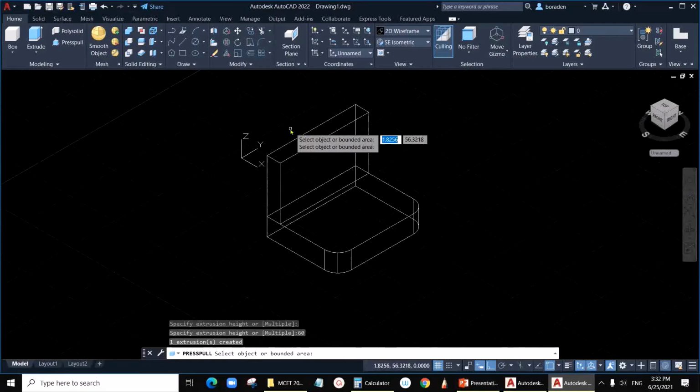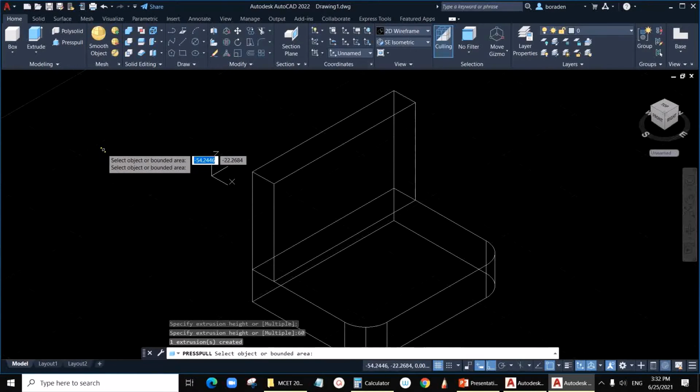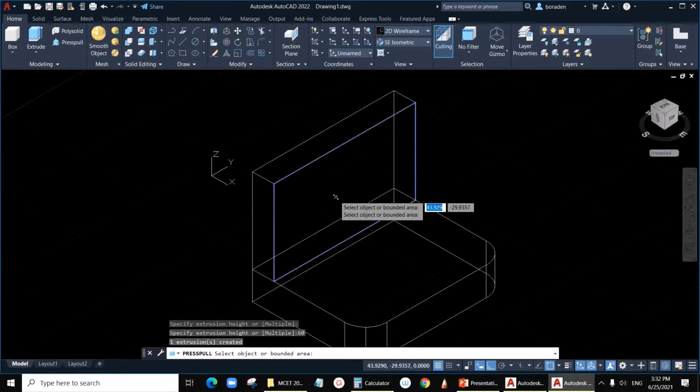Okay, so at these 2 points I will draw the circle of radius 20, but now this is my YZ plane. I want to draw the circle here on this face. So this face is in the YZ plane. So Y is okay, but I can draw only XY plane. Z is not correct. So I should rotate about Y.